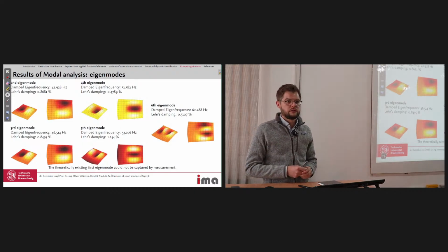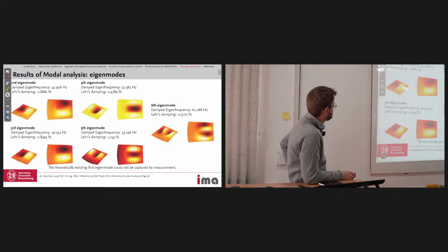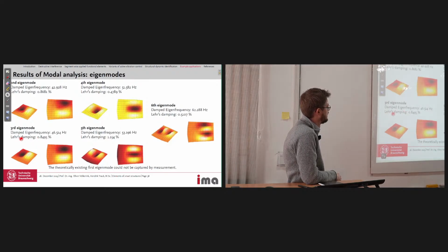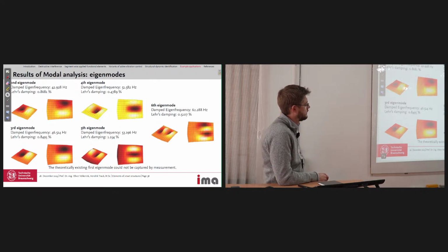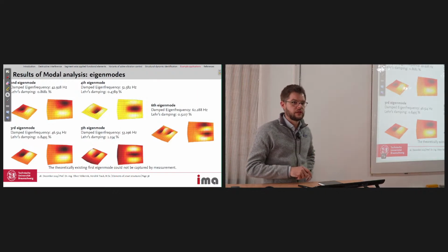Less damping is what can be said. Sorry? Less damping. I'm not sure if there's a direct translation in German. It's the Lehrsches Dämpfungsmaß. So it's how much these eigenmodes are damped by the structure without control. So how fast they decay if you excite them.